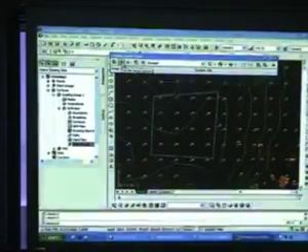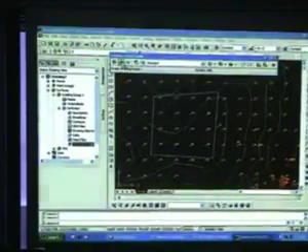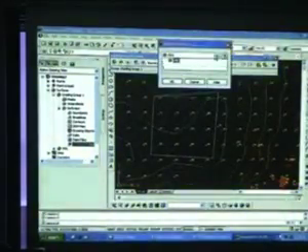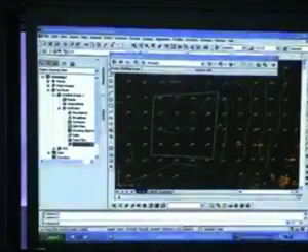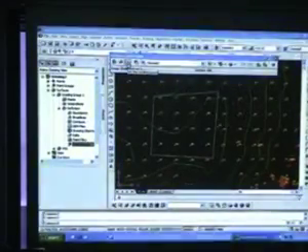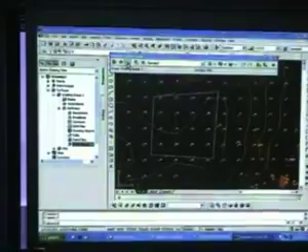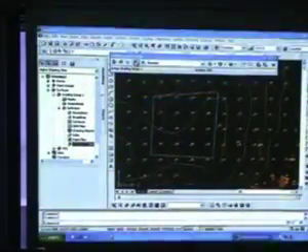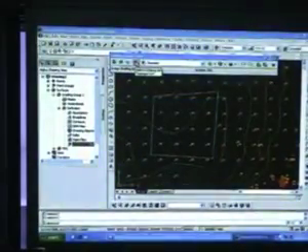Next we set the target surface, because we want to provide slopes from this platform to the original level. In case you have more than one, you need to specify the target. In this case, there's only one, OGL, so it's fine. This is where you set the grading layers if you want. The default for this template is fine. And now we're going to select a criteria set.